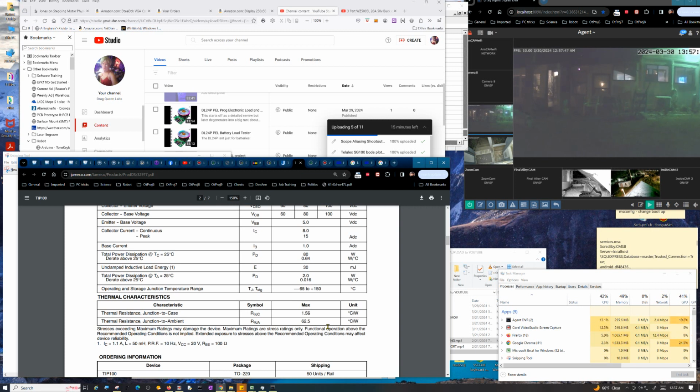If you're having failures, components burning up, maybe you're drawing a little too much current out of that op amp. It may just be 15 milliamps. Hey, it's rated at 20, but guess what? Your temperature environment's a little too hot, so it's melting your op amp, or at least causing it to misbehave big time. A lot of these components are drastically affected by temperature. You can run into trouble even if you're not melting your component down. It can really not behave like you might expect. So you never discount thermal issues as being part of the problem if you're having problems.